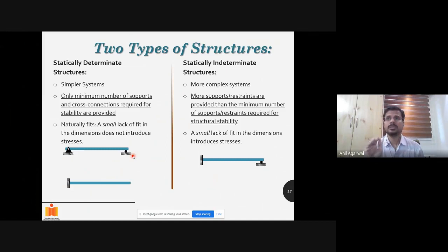Just from the equilibrium equations, you can probably not solve for deflections, because for deflections you still need the constitutive relationship, cross-section properties, and the kinematic relationships, meaning the relationship between curvature and displacement. Those kinds of relationships are still required.